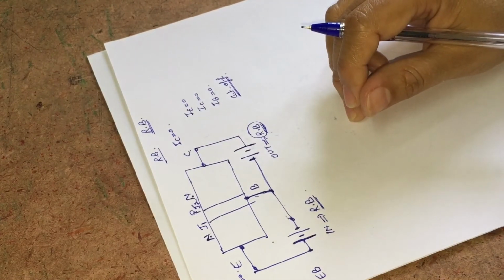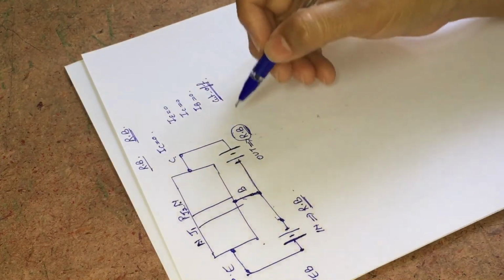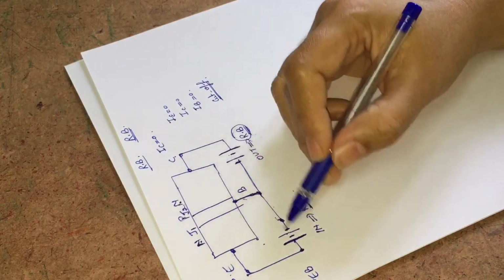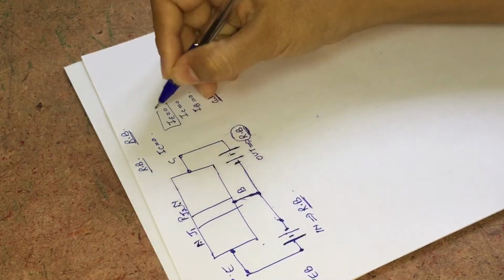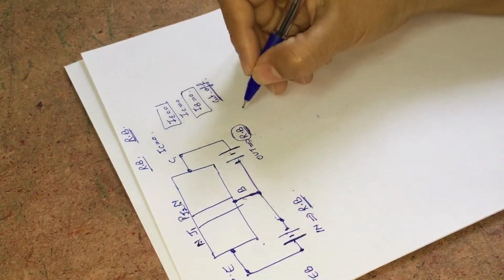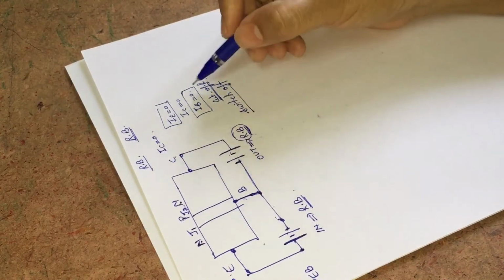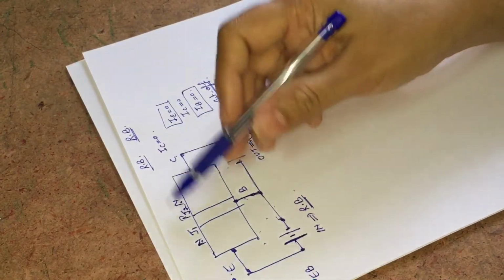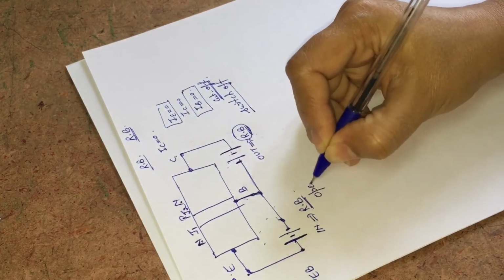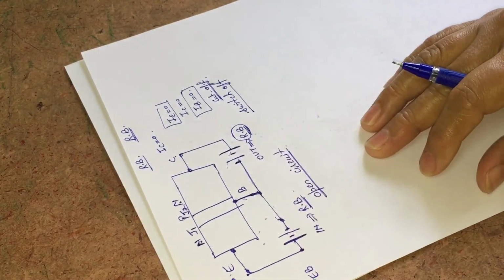This region is not of any use for transistor working, as we are not giving any input and we are not having any output. It is working like a switch that is off. It means when both sides are reverse biased, our transistor will work as an open circuit, with no current on the input side and the output side.